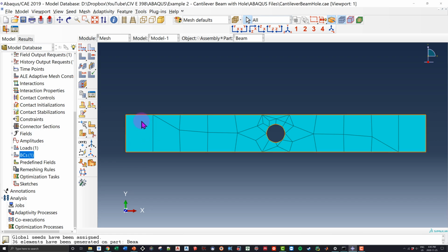So why is this important, Clayton? Well, because we are using this one element here to approximate this whole region, which can be a problem sometimes, because let's say I calculate the stress right in the center of this element. Well, since this element is so big, it's going to assume that that stress is the same throughout this entire region, which we know is actually incorrect. Of course, there's going to be a change in stress, whether I'm looking at the bottom of the beam compared to the top, or vice versa if I'm looking laterally.